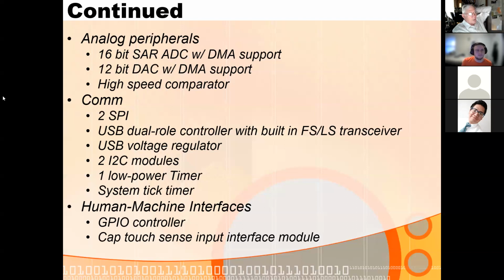So I use that on the tilt table. We're averaging, I think, maybe even 32 readings, because we have time to take that many readings and more during a PWM cycle, because the PWM cycle is really slow. In the tilt table software, we're running it at about 10 or 12 milliseconds.